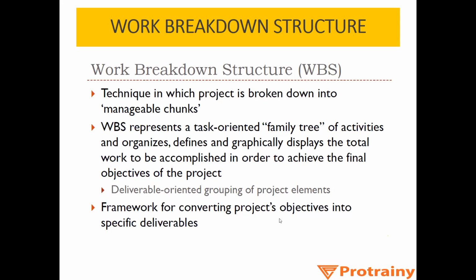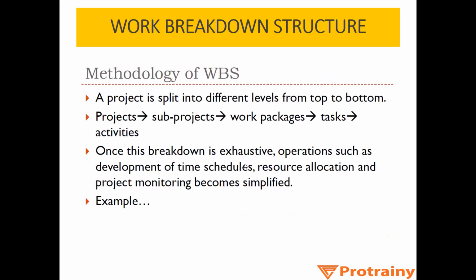Now we'll see the methodology, how we prepare a WBS, and finally we'll see some graphs of different WBS. Methodology: a project is split into different levels from top to bottom. First the project will be divided into small sub projects. For example, substructure. Substructure is any work at ground level or below the ground level. Then there is superstructure, from the plinth or ground floor till the top. So this becomes the first subdivision, substructure and superstructure.